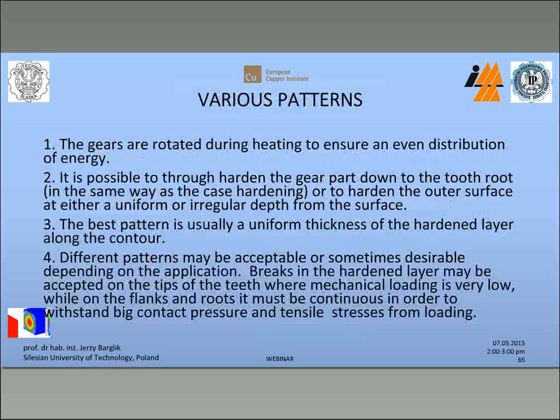Yes, of course it is. There are different patterns received during induction surface hardening of gear wheel. The best pattern is usually, of course, a uniform thickness of the hardened layer along the contour. But, of course, it could be very different patterns.